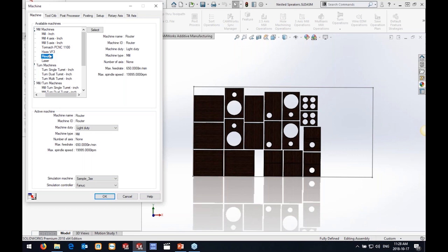Now this is different milling type equipment, but the same could be used for mill turns. Say, for instance, you've got a mill turn with a C axis and a mill turn with a Y axis as well. You might want to save strategies associated with different types of mill turn equipment. So on my mill turn I automatically always do free moves. On my Y-axis machine, I will automatically do fixed, because I've got that Y-axis capability, so I can run it across the part and go from there. So you can save those settings back to the database and reuse them based on the machine-specific setup.